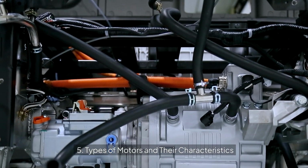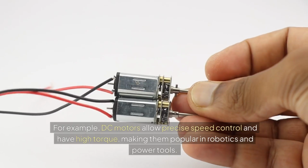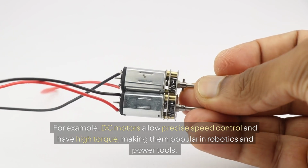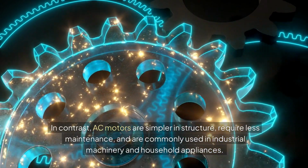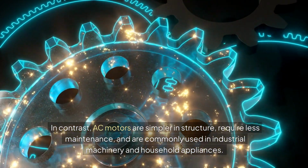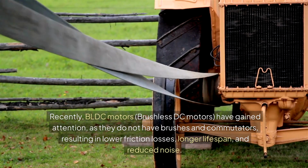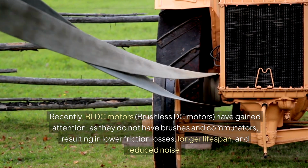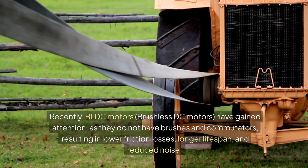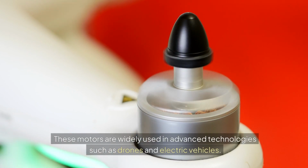5. Types of motors and their characteristics. There are various types of motors, each optimized for specific applications. For example, DC motors allow precise speed control and have high torque, making them popular in robotics and power tools. In contrast, AC motors are simpler in structure, require less maintenance, and are commonly used in industrial machinery and household appliances. Recently, BLDC motors, brushless DC motors, have gained attention, as they do not have brushes and commutators, resulting in lower friction losses, longer lifespan, and reduced noise. These motors are widely used in advanced technologies such as drones and electric vehicles.